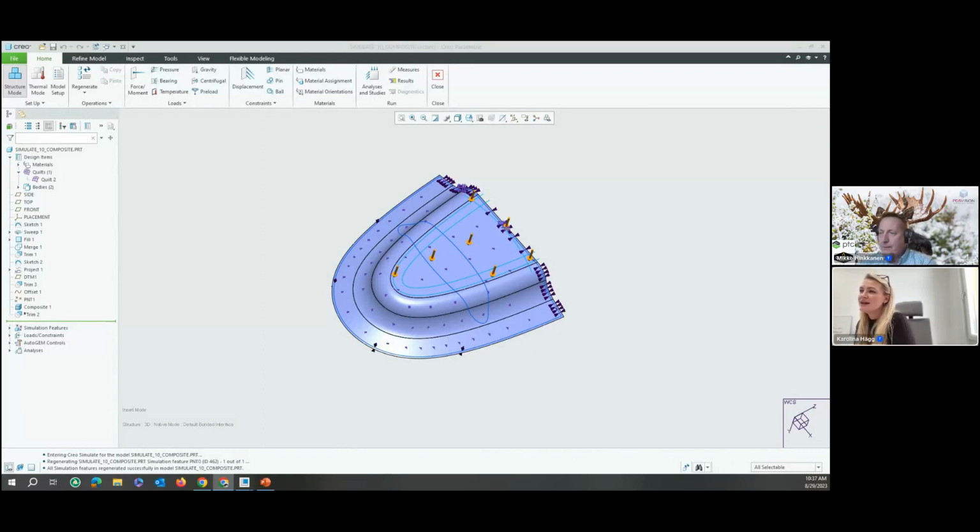So we have this one: Can you read HDF5 from composite design to ANSYS Mechanical? Yeah, very good question. If you do a composite design, you can push the whole definition, the geometry and the materials and the material orientation and layup sequence, to this specific transfer file, which is then readable by most composite calculation applications if you want to go for really in-depth analysis. And ANSYS Mechanical happens to be one of them. So yes, it's possible.